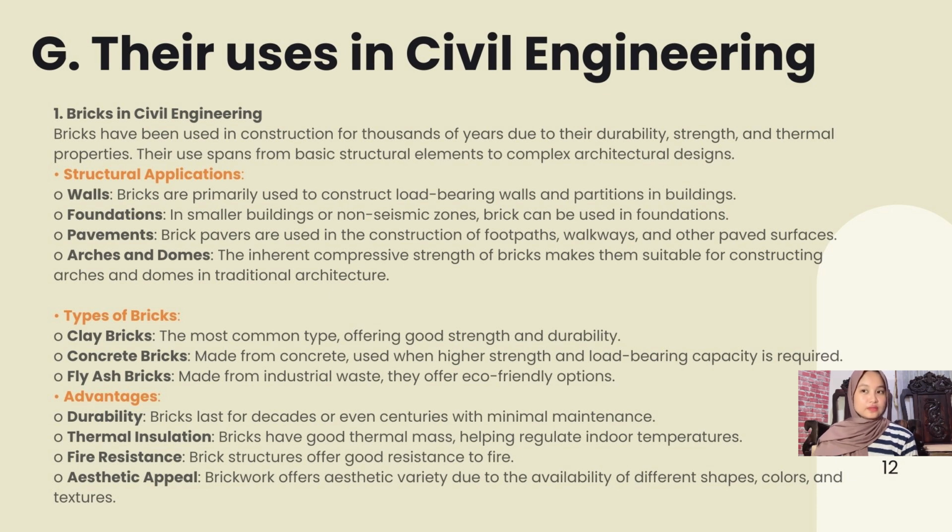Types of bricks. There are three types of bricks. The first is clay bricks, the most common type, offering good strength and durability. Second is concrete bricks, made from concrete, used when higher strength and load-bearing capacity is required.